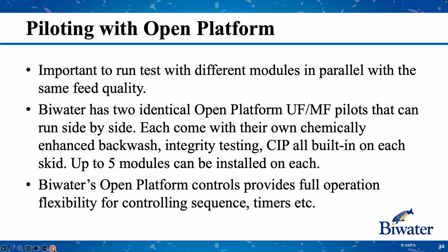So Bywater has a couple of identical open platform UF/MF pilots that we run side by side. They are complete integral units. They have all the components for the complete operation, backwashing, maintenance, cleaning, or CIP cleaning of the modules, all in a compact skid.